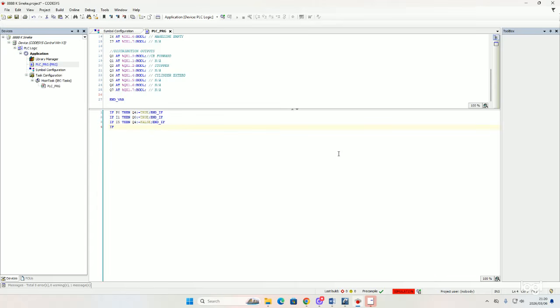Okay, then what's opposing our conveyor belt is I2. Our I2 is always on, meaning it's normally closed, right? So in ladder logic, we don't negate I2 because current is already flowing. So when activated, it cuts power. It stops the current from flowing, right? Because when a part gets to I2, then the conveyor stops. So our conveyor, which is Q0, if I2 is activated, then Q0 will not be true but false.